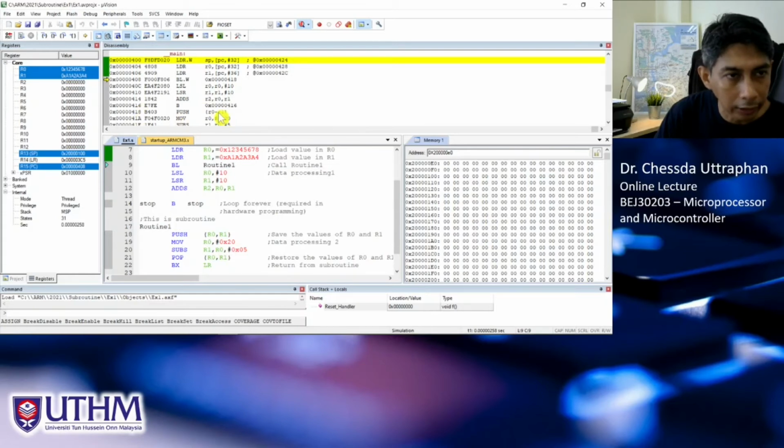This is the address of our subroutine, which is 418, 41A, all in routine 1. So you see the address of the subroutine is not in the main area of the program. After we execute the BL, the next instruction to be executed is LSL, or logical shift left, which is this one.